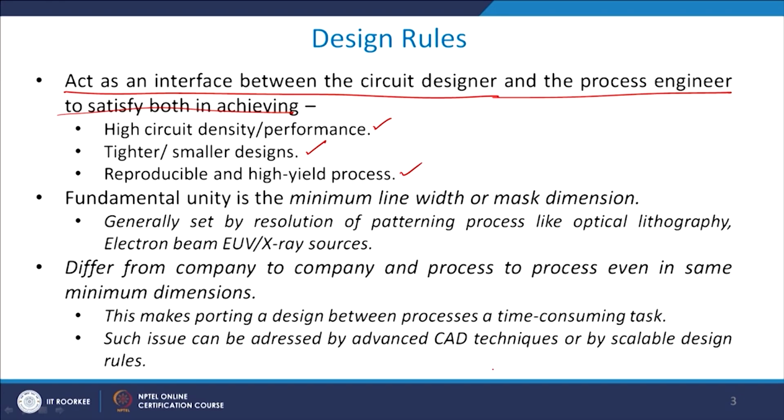Why are they required? They are required because you require a very high performance, which basically means that, for example, if your contact is very large in dimensions, you eat away into area, but again if it is very small, you then have larger resistance offered by the contact. So, you need to optimize the contact area, and the process people have already optimized the contact area for you. Say the metal contact should be, say, 0.5 micron by 0.5 micron. So, they will let you know, and then you design that much exactly onto your profile and you get the best results.